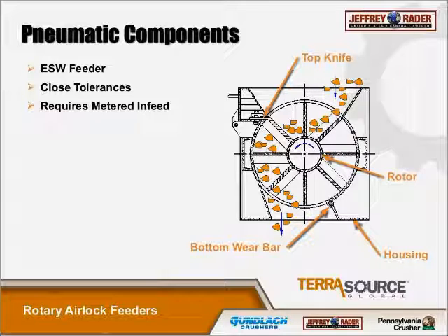ESW feeders require a metered in-feed of material. It needs to be controlled. It's not really a feeder in the true sense of the word. Think of it more like an airlock that just introduces material to the high-pressure conveying system.